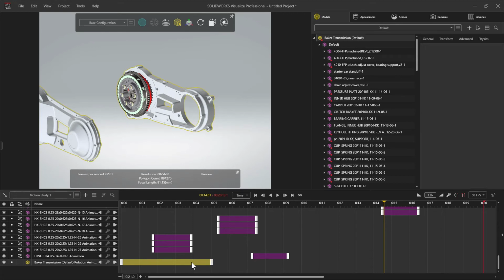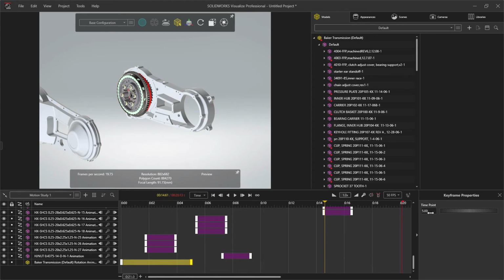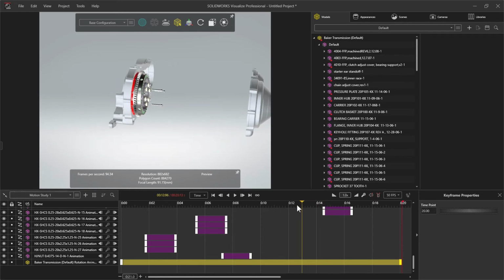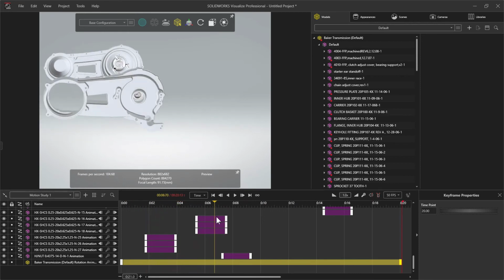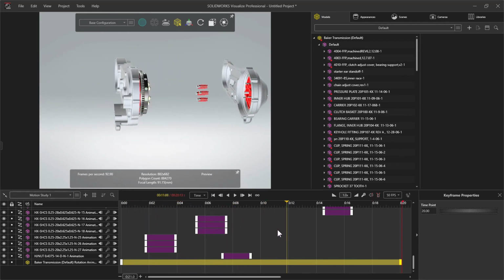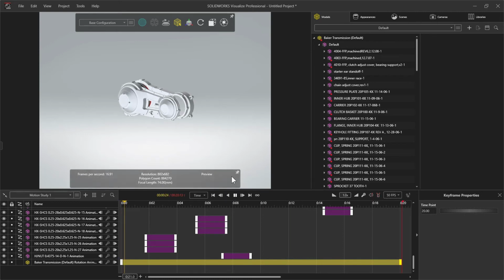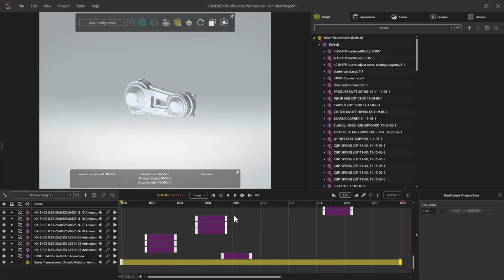You can double click on these and wake up properties. I can click on the endpoint and tell it to be, at this moment here, 20 seconds. And now what we see is the model rotating as everything explodes. Alright, so if I zoom out, we'll be able to get a better idea of what's happening here. Right, so we've got some really cool compound motion with only a few steps.